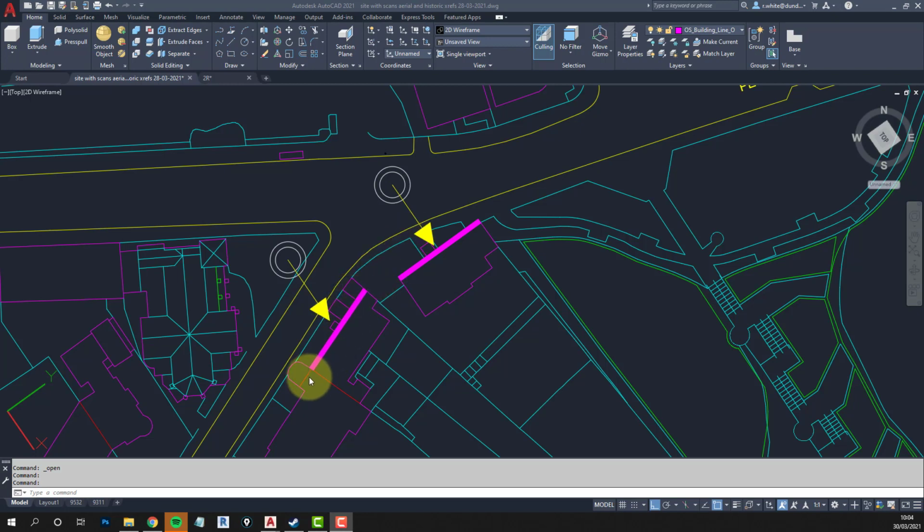Because they're at different angles, I would be put to quite a lot of work to generate the elevations for that particular building. So we can use the Flatshot command to generate the squint view of the neighbouring building, and vice versa. If we were generating this one, Flatshot would give us this one at the squint angle.